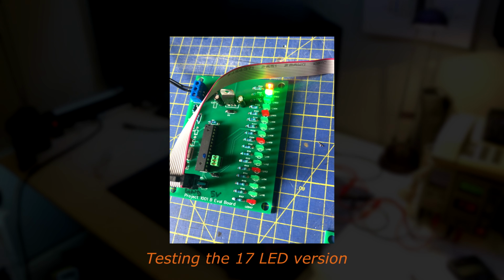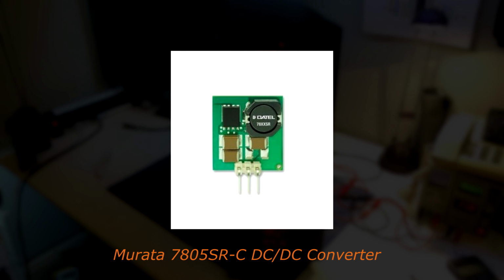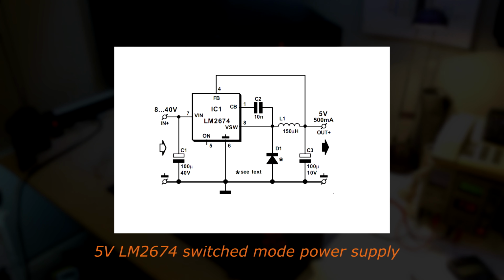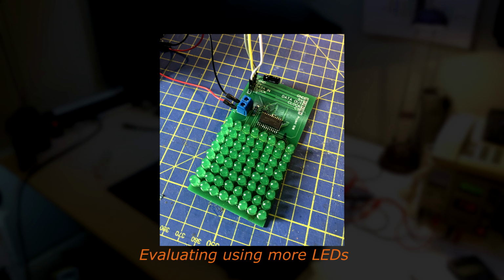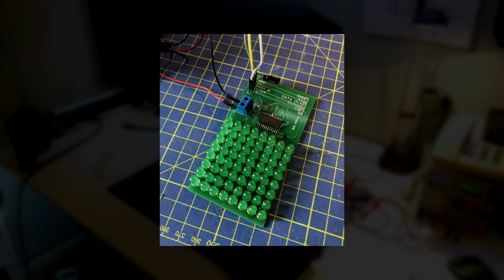I'm quite happy with the end result, but if I was to respin the board I would do things a bit differently. I would perhaps use a switch mode power supply or something less wasteful than a linear regulator, and also use surface mount components where convenient. I have a loose plan in the future to implement a MAX7219 LED driver like in the CM5 Lights themselves to drive more LEDs, but I'm not quite there yet.